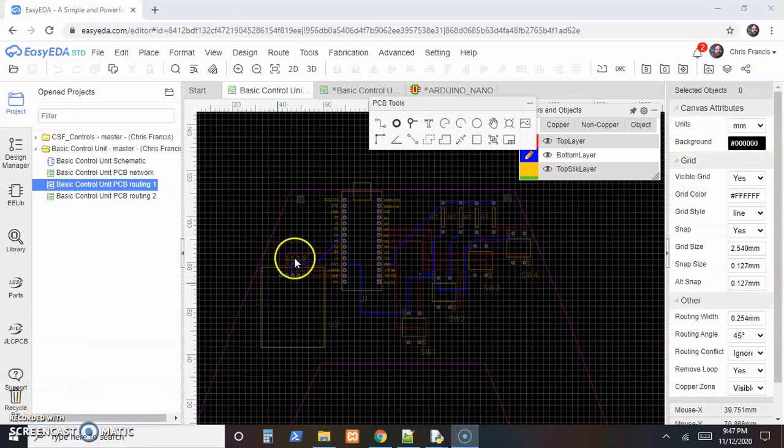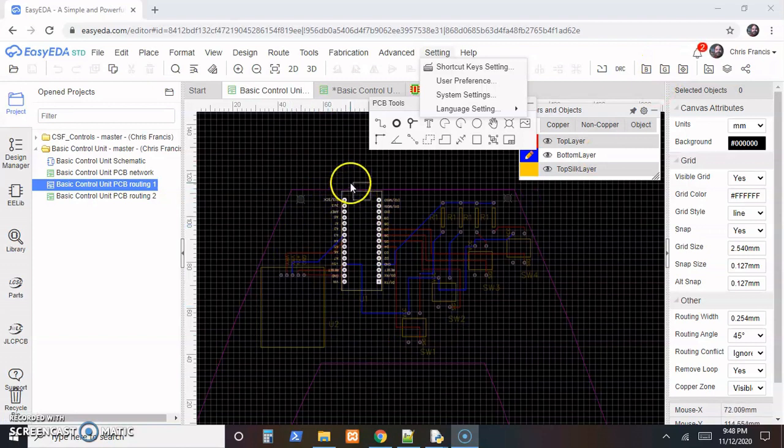So I had a slight issue I had to come back and modify. Here, the outline, which is just marked on the silk screen, what gets printed on the board, extended beyond the outline of the board, which is no problem when we order the files. Ordering the Gerber files from the factory, they would just stop printing at the side of the board.